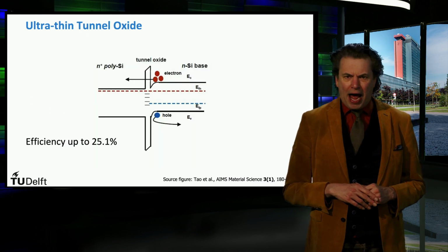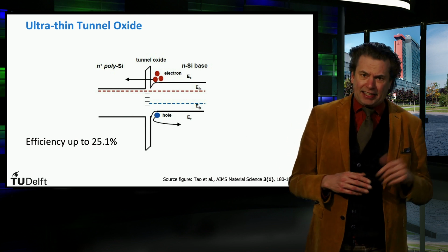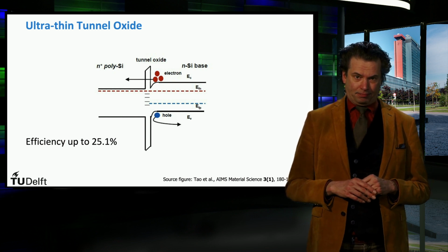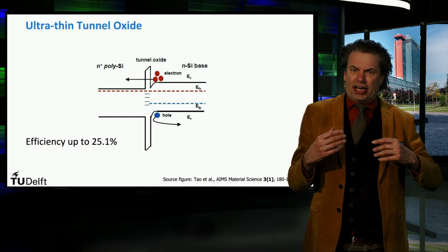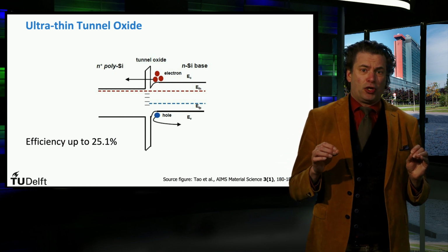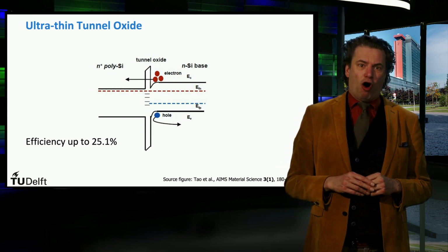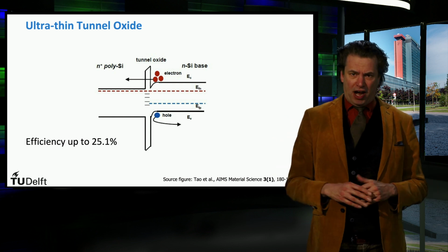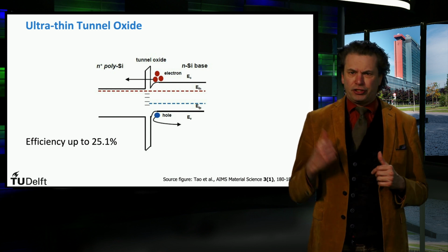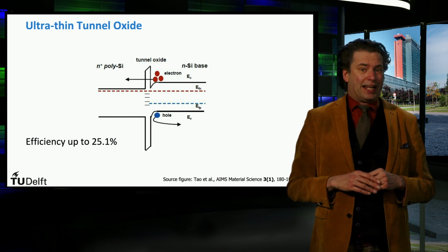The band diagram of the back contact demonstrates the principle. Left side is the N+ layer and the right side is the n-type crystalline silicon. Now, since the oxide layer is present, it is almost impossible for the minority carriers, which are holes for the n-type wafer, to reach the back contact of the cell, as they cannot pass the potential barrier introduced by the oxide layer. In addition, you see in this example that the electrons experience a smaller barrier than the holes.